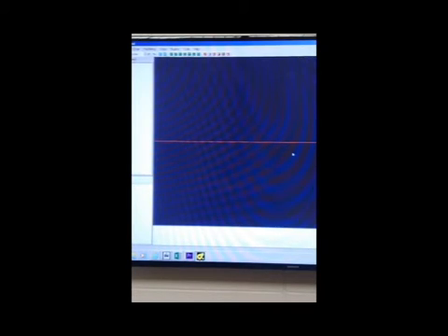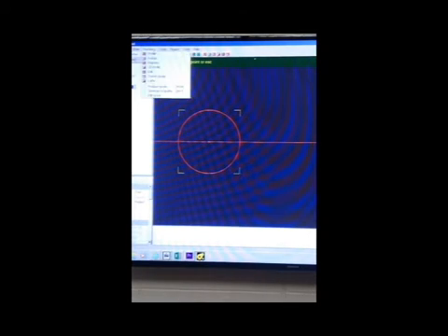So what I was hoping that you guys could do is to do something really simple, like this, for instance. Choose a circle. Place that circle somewhere on the screen. And then you can go into the machining tab and actually create the G-code from that profile. And once the G-code's created, you could save it to a file on your desktop and submit that as your assignment.